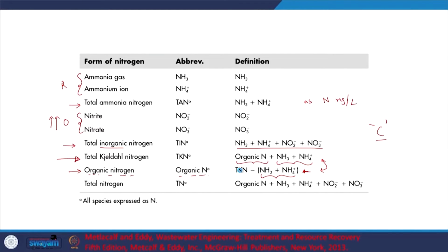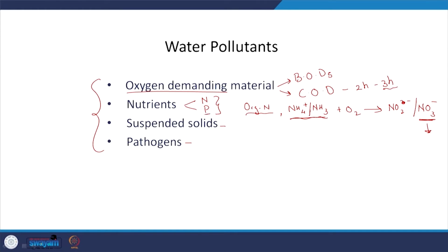And then I believe we were looking at phosphorus. In the context of phosphorus, we looked at 3 aspects, right, but typically we looked at orthophosphates as being of primary interest to us, right, as in H2PO4 minus, HPO4 2 minus, PO4 3 minus and such. Why is that? Because they are very soluble and relatively more reactive, as in the relevant bacteria can make use of these soluble compounds relatively easily.